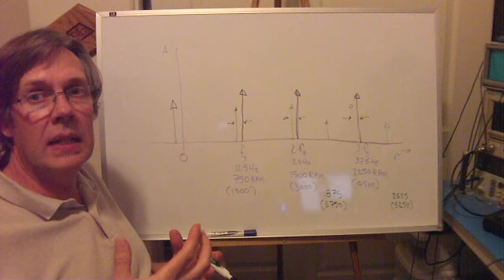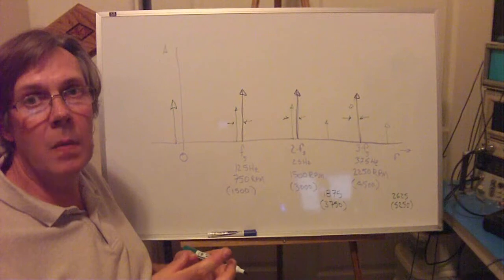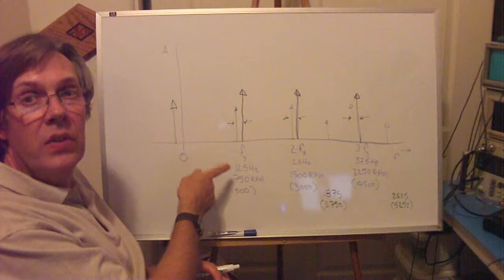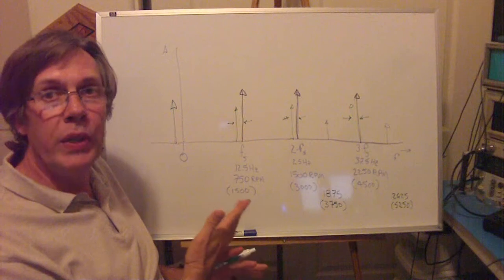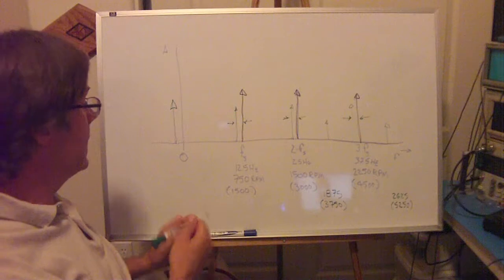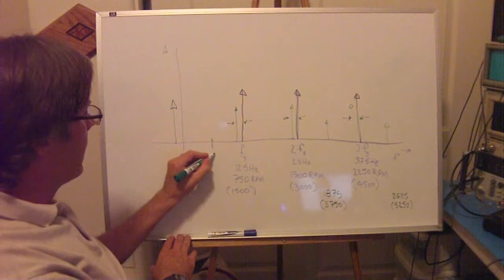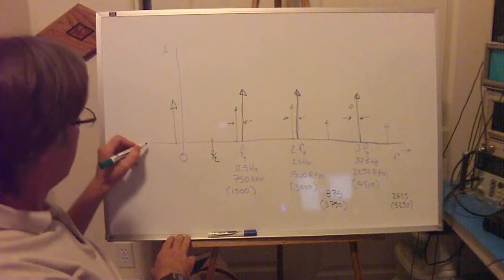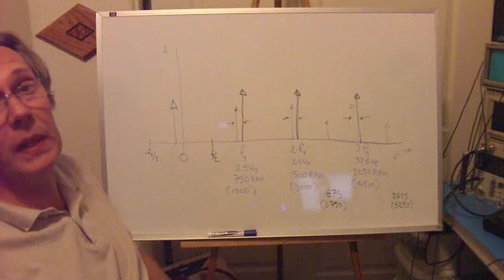turning at minus 50 RPM, that's what it would look like. So again, because it's a rotating system, a circular system, or if we had complex samples with a real and imaginary part of any kind of system, we can tell negative rotation from positive rotation, or negative frequency from positive frequency. So when we have this sort of complex or rotating system sampled, what we can get then is what we call our baseband, or our real region, I guess, which is from f sub s over 2 to minus f sub s over 2. That is what looks like reality.